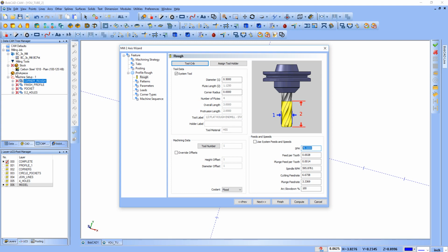This material, you can select your material. I've never done much with it. I cut a lot of aluminum, and for the most part, I kind of know what I'm using RPM wise, and certainly that's relative to material and the tooling that you're using. So I would recommend looking at your tooling manufacturer. Most people are pretty good about having recommended SFM right there, that's surface feet per minute.